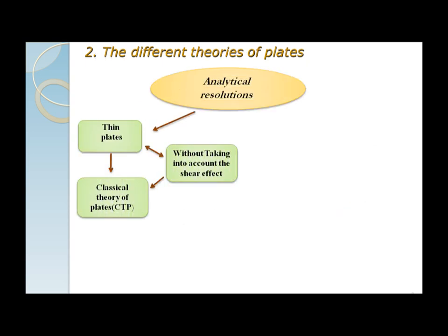For an analytic resolution, several theories were proposed. For the thin plate, we have the classical plate theory of Love-Kirchhoff. In this theory we do not take into account the shear effect. Therefore, the deformation due to shear is negligible.